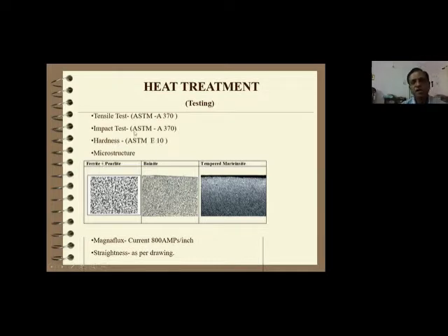And after carrying out the different processes and conducting tests, some jobs are randomly cut for destructive testing for microstructure analysis. So that microstructure, if it is ferritic pearlitic, is normally like this. You can see this white is ferrite, and the black is the pearlitic structure. Then this is the bainitic structure, and this is a tempered martensite structure with a little bit of partial decarb near the surface. So these are varieties of structures based on the final requirement.